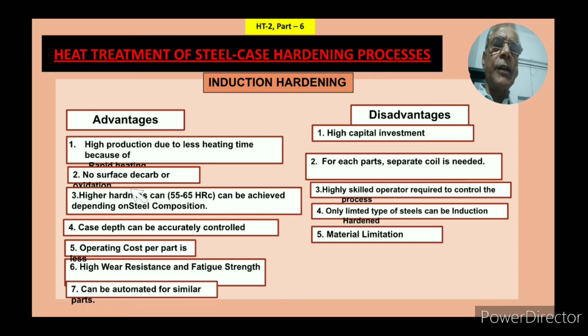No surface decarb or oxidation. There is no surface decarb, and there is no oxidation, because the part is exposed for a very small time, in terms of seconds. So it is not getting exposed to air or other things. So there is no chance of any oxidation or decarburization.